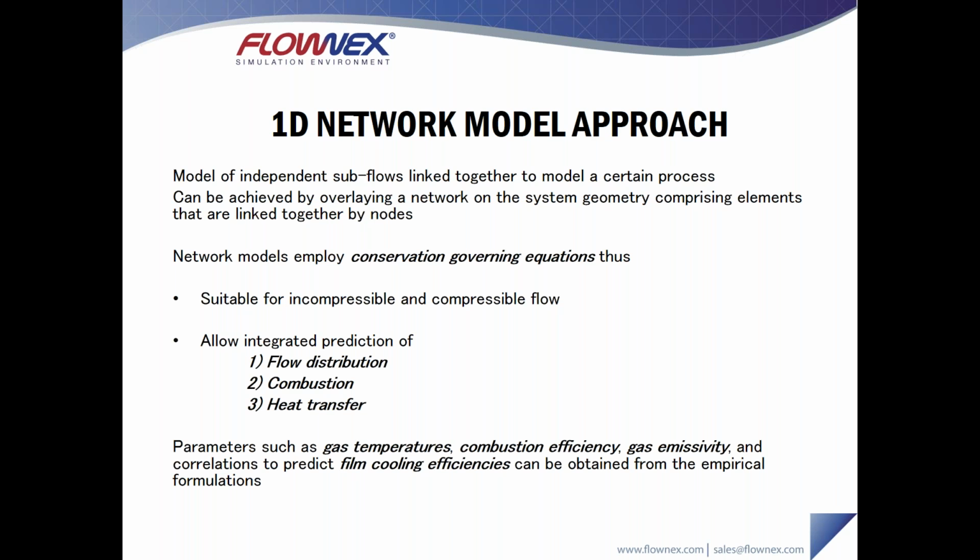So what is the 1D network model approach? You can think of it as a set of independent subflows linked together to model certain processes. This can be achieved by overlaying a network on the system geometry, so basically defining the geometry in terms of a 1D model, and this typically comprises elements that are linked together with nodes.